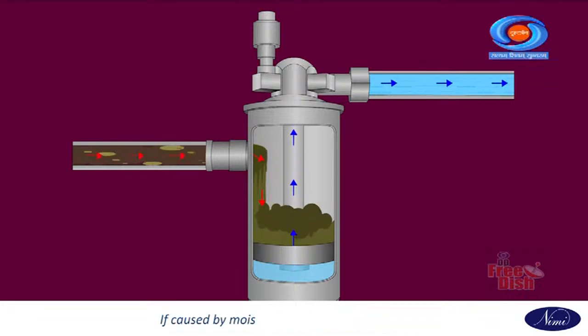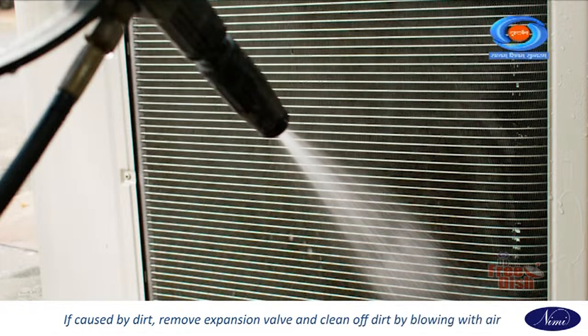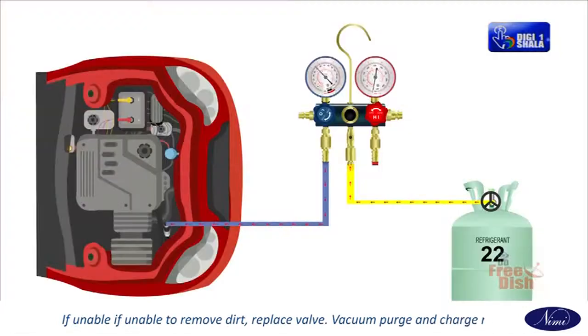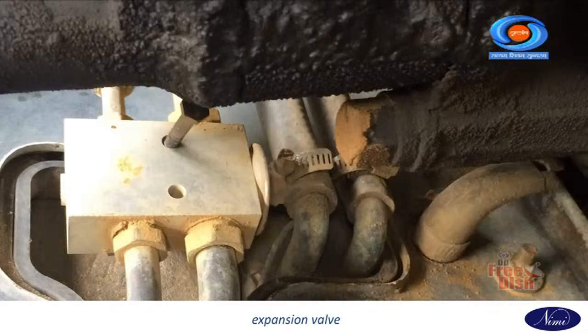If caused by moisture, refer to procedure step 2. If caused by dirt, remove the expansion valve and clean off the dirt by blowing with air. If unable to remove the dirt, replace the valve, vacuum purge and charge new refrigerant to the proper amount. For gas leakage from the heat sensing tube, replace the expansion valve.